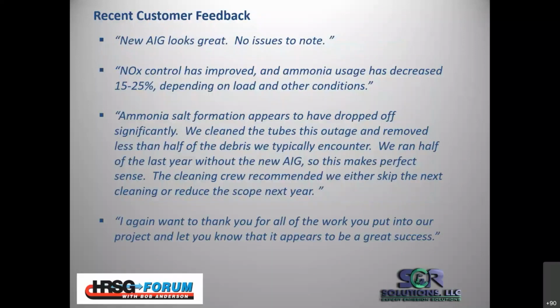And according to the customer, the ammonia injection grid retrofit went very well. They had improved NOx control, and that ammonia salt formation dropped off significantly. So from having to clean the tubes once a year, they have stretched that out to an as-needed basis. They're not even doing it on a regular basis because the amount of ABS buildup on the tubes has dropped off dramatically.